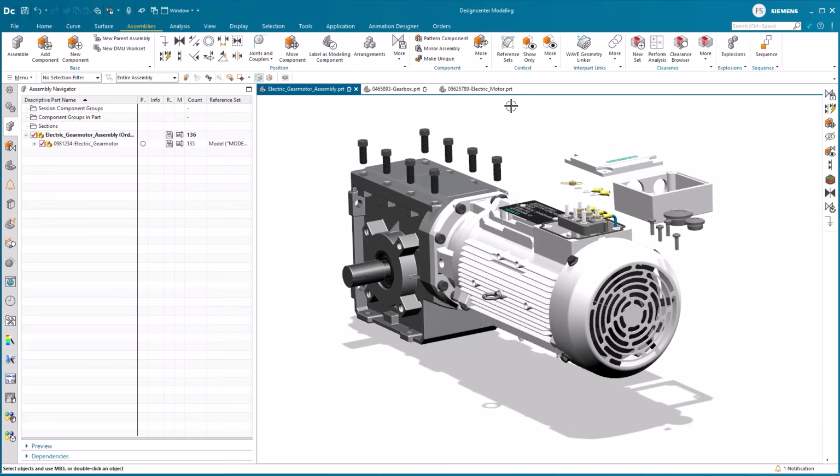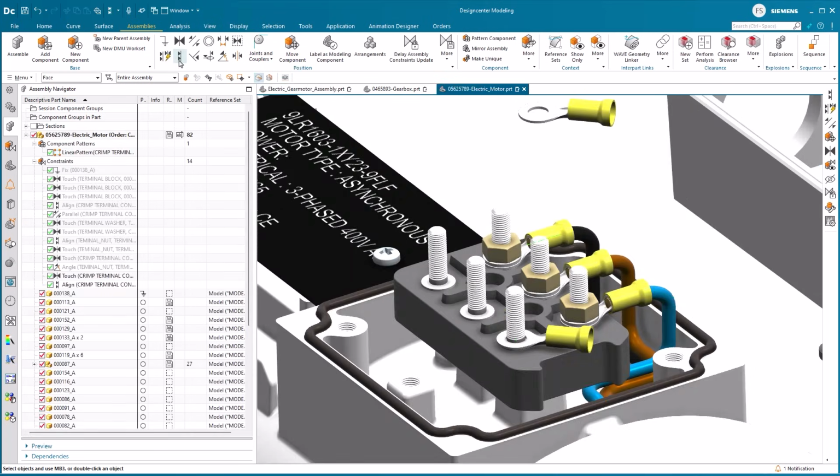We will be touching on creation of valid constraints only, improved behavior of show constraints of component, copy and paste of component or subassembly's original location, auto align and the possibility of utilizing drag and drop techniques. New here is that adding a constraint that cannot be resolved or a conflicting constraint is no longer possible. This helps the user to stay out of potentially timely downstream and upstream issues.